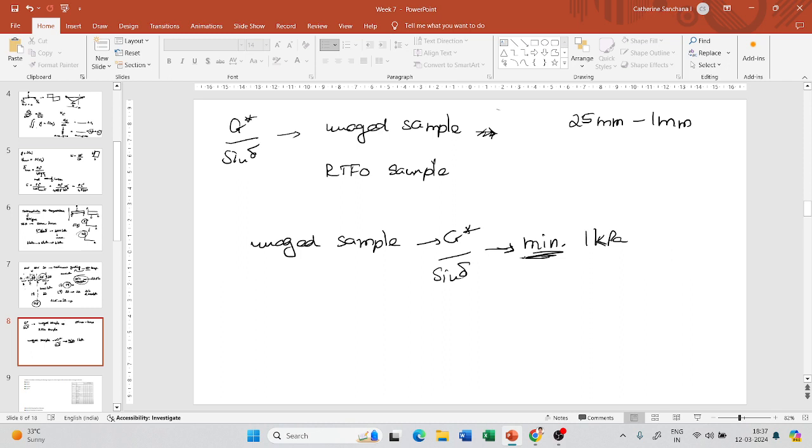That is why we give a minimum value for high temperatures and a maximum value at intermediate temperatures, because at intermediate temperatures we want it to be sufficiently soft. It should have at most this much stiffness. If it goes beyond this, if it is more stiff, then my bitumen is going to fail by fatigue. At high temperatures it should have at least this much stiffness. If it does not have even this much stiffness, it means that my bitumen is very soft and will undergo rutting.